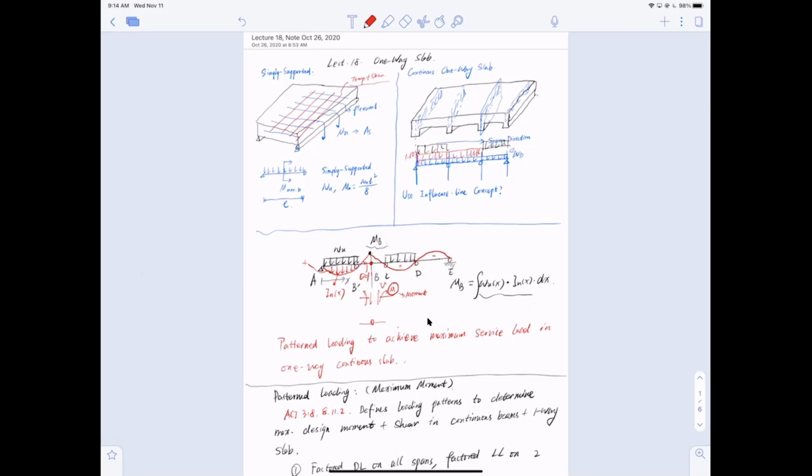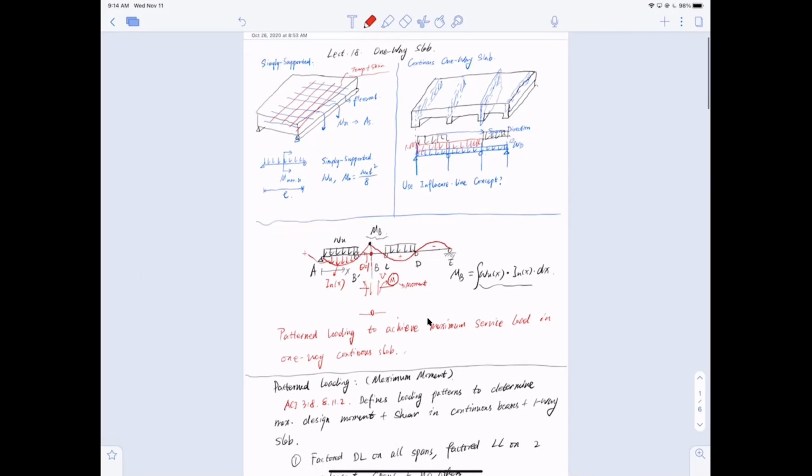When we say flexure reinforcement, that means the bending direction is along one direction. I'll use a different color, blue, for bending. You'll notice that in some of your one-way slab homework grading you might have lost some points. I will talk to the grader and correct some of the answers. But like I mentioned again, there's only one direction for bending. I draw it here as a continuous one-way slab, as you can see on the right-hand side. This is the bending direction.